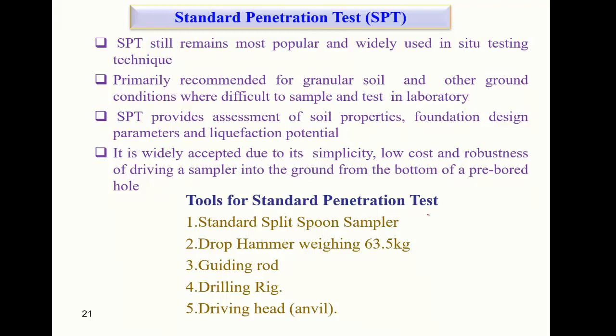It is primarily recommended for granular soil and other ground conditions that are difficult to sample and test in the laboratory. We know that with a disturbed sample we usually cannot do some of the tests in the laboratory. So where you don't need any laboratory test, or it's difficult to conduct one, you can also use it.